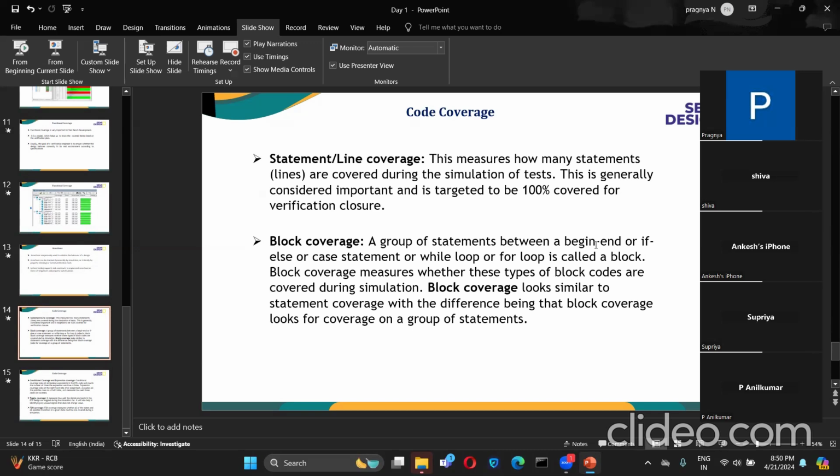We can think so, because a self-checking testbench is nothing but writing, for example, the scoreboard logic which we have. What will we do in the scoreboard? We compare the expected data and actual data, right? The same thing we mention in the particular test case itself. We write some kind of checker mechanism, right? Likewise, assertions also do this, but with some different things. We use sequences and properties, and this will apply to all the tests also. It will be applicable if we include these assertions in our top level.